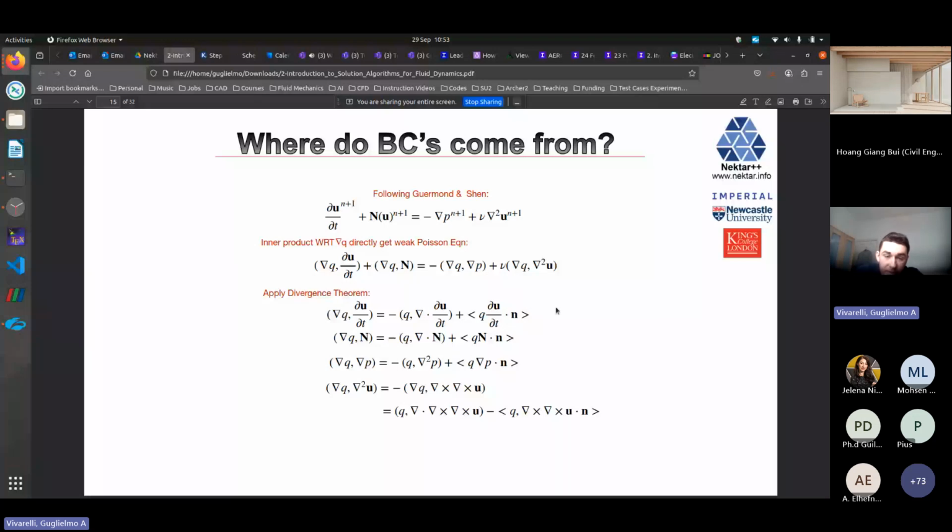And you can reduce this, utilizing the method of weighted residuals, which Mohsin has outlined earlier on, to the one below, which is just the gradient of the basis function multiplying each and every term of the incompressible Navier-Stokes equations. So that's a shorthand version. Each and every one of those is just the integration over the domain of the gradient of the basis function dot producted with each and every one term.